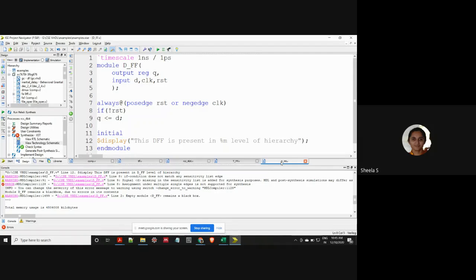So that is why we can say that not all designs that can be simulated can be synthesized, but all designs that can be synthesized can be simulated. It means if we are able to synthesize, we can generate the circuit. When the circuit is generated, obviously we can check the output. The output may be correct or wrong, but we can still check it. If we are not getting the required output, some logic mistake is there, but still the circuit can be generated.